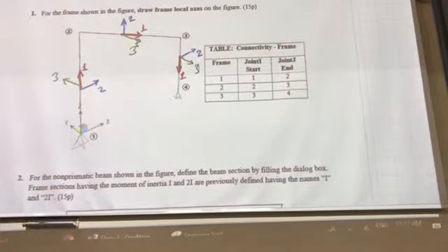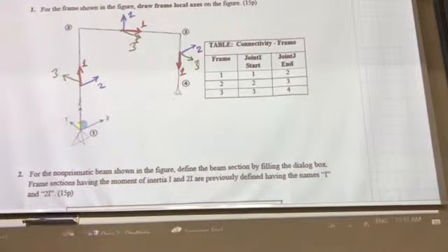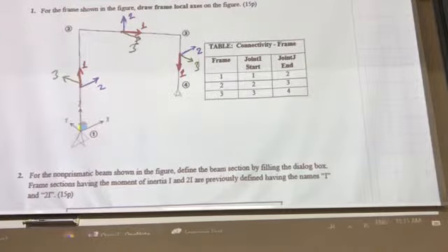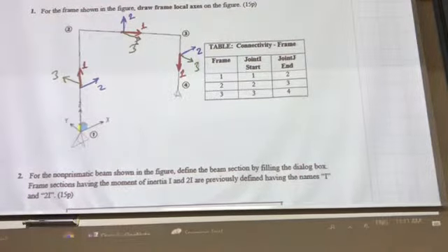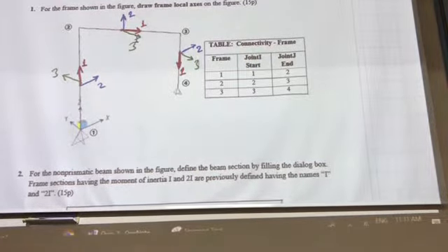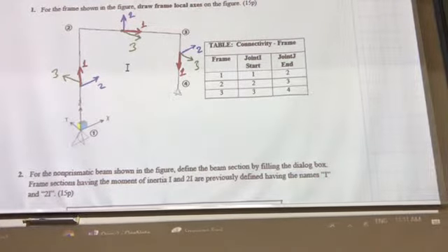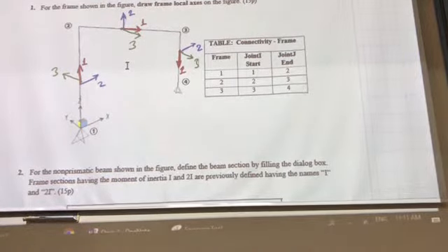For example, are you going to look at moment 3-3 or moment 2-2? What is the direction of moment 3-3 and 2-2? These will be important for 3-dimensional structures. For 2-dimensional structures there is no problem. For 2-dimensional structures lying on the xz plane, axis 3 is always perpendicular to the plane.